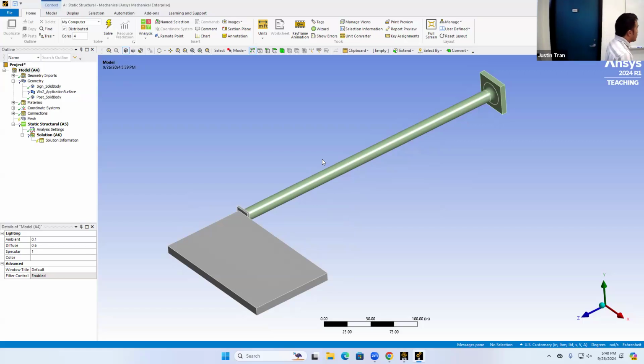All right. So first thing we're going to do, if you remember in activity 2, when we added our aluminum material property, we needed to assign that material to certain parts of our geometry. Back in activity 2, it may have seemed a little bit tedious to do that. We spent all that effort to add in the material and then we have to assign it. The reason ANSYS does that is because if you have a multi-part assembly like this, you can actually assign different material properties to different parts of the assembly.